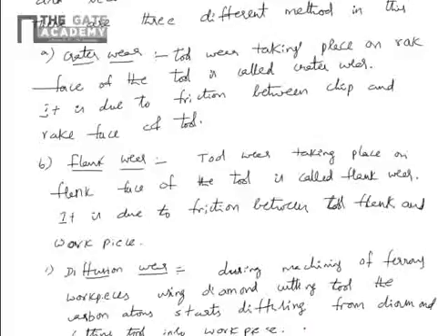After some point of time, a lot of atoms will move from the tool to the workpiece, so there is a loss of material, wear of the tool material. It happens with materials that have chemical reaction and form a new compound. This is called diffusion wear, which is a case of diffusion of carbon atoms from the tool to the workpiece.